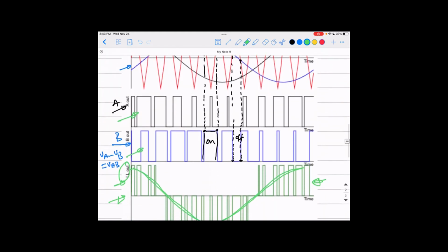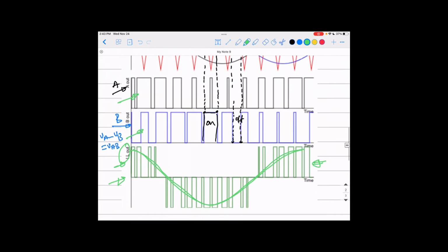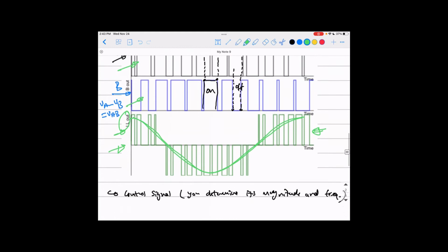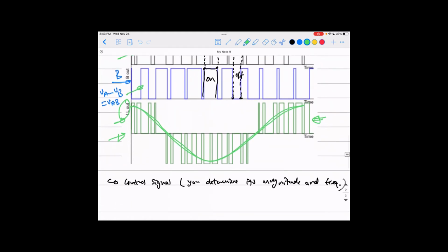Actually, that's a problem with using power electronics, because power electronics all the time generate more harmonics in the system, and these harmonics are not good. That means your waveforms are not purely sinusoidal, but rather look like what you've seen here. But like I said, you can use filters to filter out as many harmonics as you can. You will not be able to filter all the harmonics, there will still be some harmonic content, and this is not good for the devices.